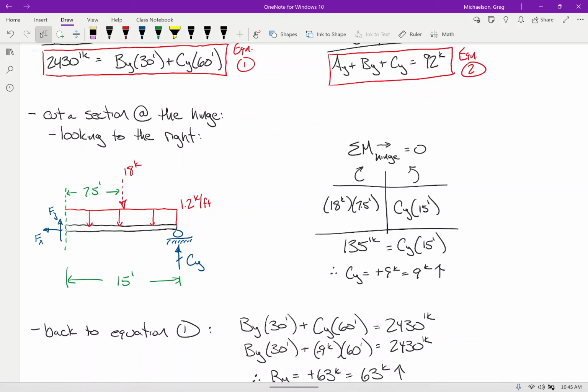Is the material expensive? Well, if we're talking about steel, it's a function of how many bolts you put into a connection. If you design a connection to resist shear and moment, that's more bolts, more time on the site. We will spend a great deal of time talking about that in steel design, about how to configure connections that use either bolts or welds.